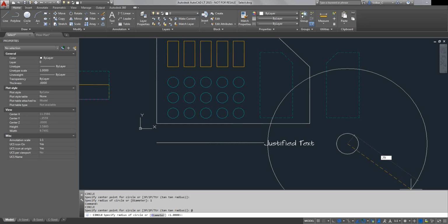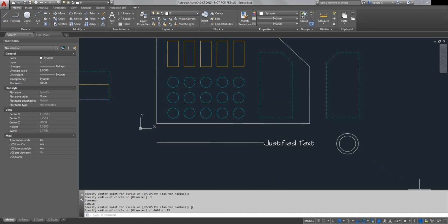Yeah, 5. Had to find it on my keyboard. I'll repeat it again, @ symbol, enter, 0.5, enter. So just a quick way to reuse that last point. I mean, I could have used offset in this example, but I have fun with this particular function, so I have to show it.